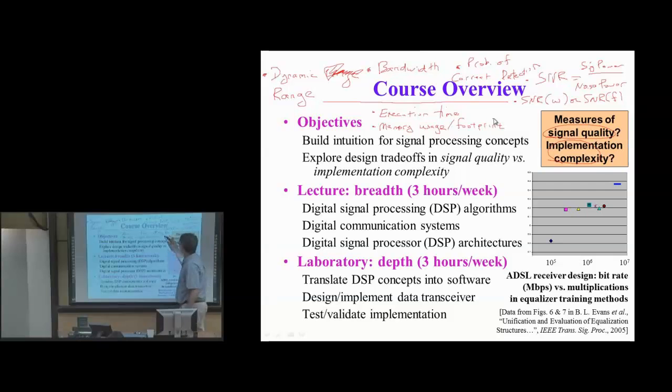So memory I/O rates becomes very important. Again, with hard real-time systems, we want to guarantee data getting off-chip to on-chip in a reliable manner, working on that data and getting it off-chip to meet a specific deadline all the time. Okay, so there's a lot of hardware support to make that happen, and we'll talk about that as we go.